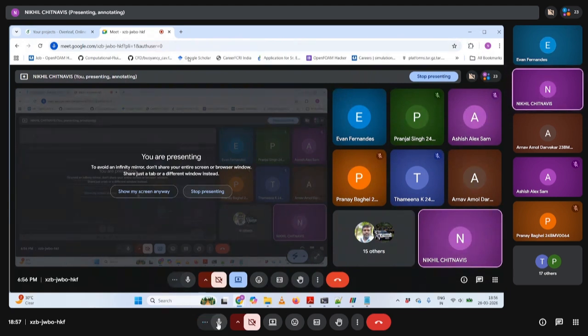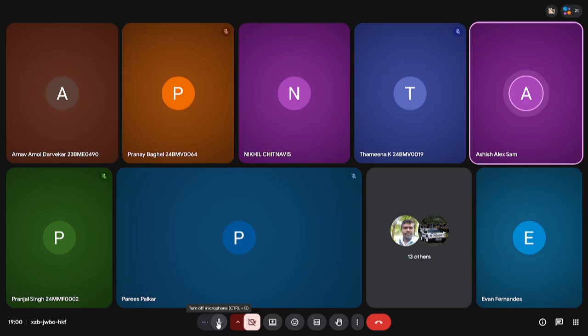So the thing is, when I tried searching for the topoSet dictionary online, like how can I define various surfaces within my STL file, it mainly just gave me solutions for boxToCell or cylinderToCell.